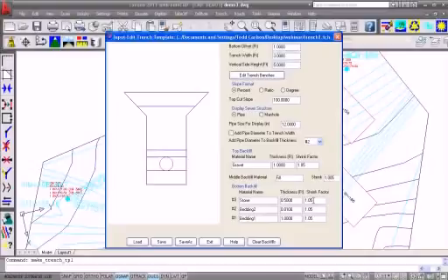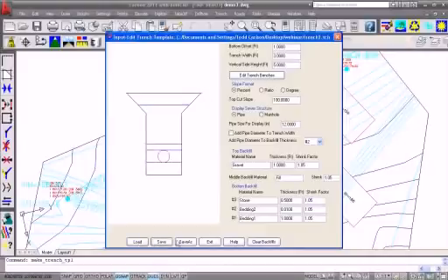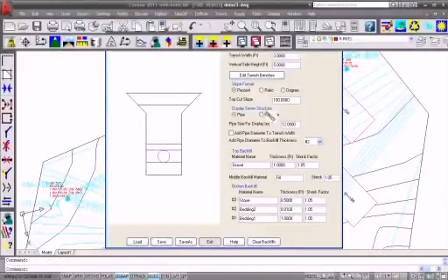Yep. And something else that we've added new to 2011 is that, for our cut fill volumes, we've always had a shrink and swell factor on the cut and fill, and that's something that we've added here for the backfill quantities. So this is a multiplier. 1.05 would be, the shrink factor would be 5% on this. Let me save and exit.